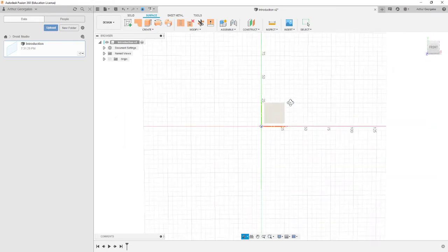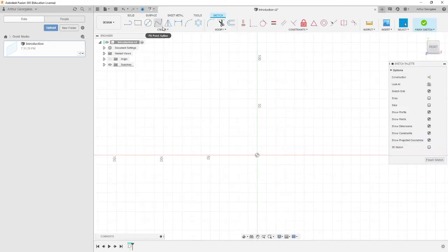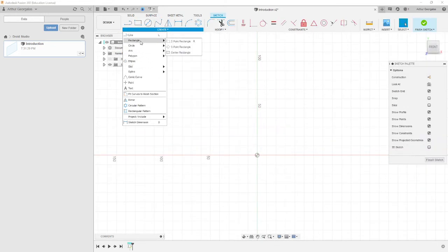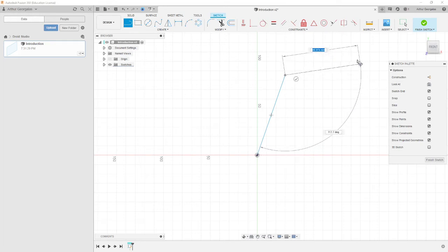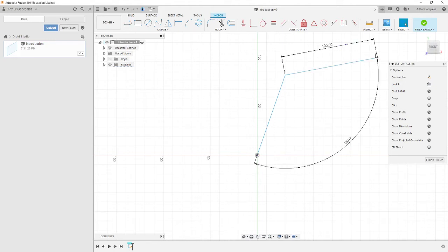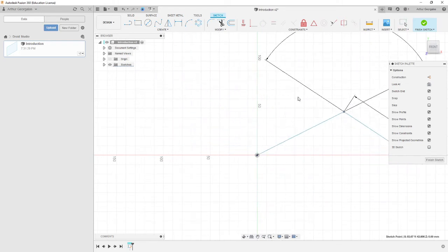So then, like SolidWorks or other CAD, you need to select a plane to sketch on. So we select the front plane, and we've got pretty much all the same tools: lines, rectangles, circles, arcs. It's all the same. We'll find that it does give us these straight up options for inputs as well. So if I type in 100, press tab and press 120, it brings it 100 mil at 120, and well, apparently not. 100 mil, tab 120, enter, and it automatically defines it. That can be useful. I generally don't do it that much, but it is what it is.